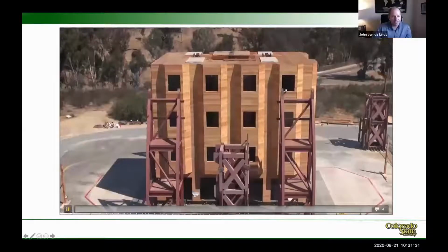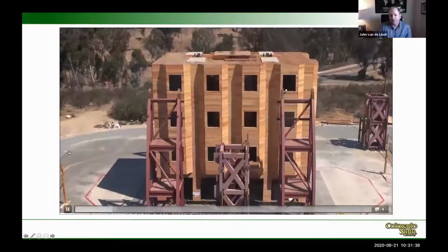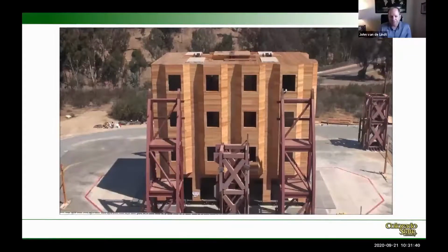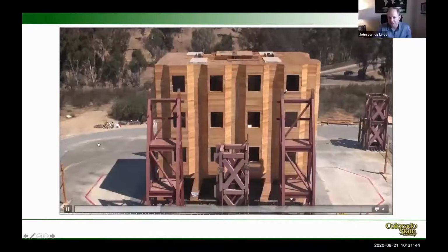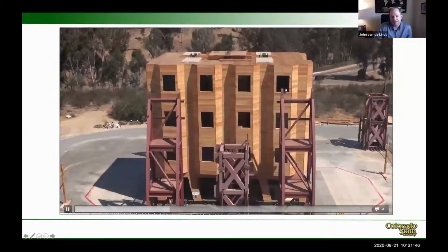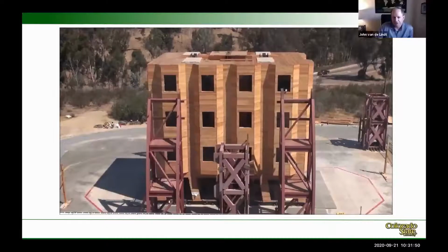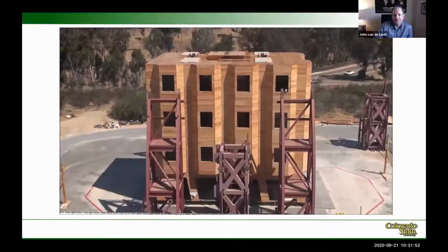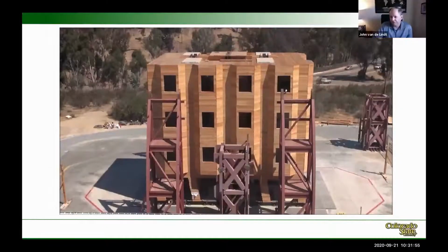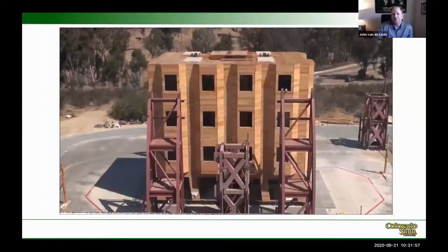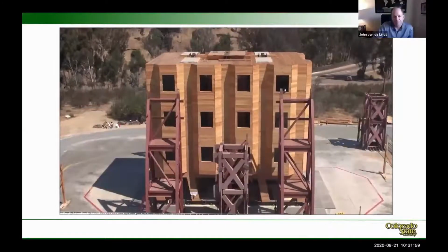So here is the test. I've taken away the sound just because it causes some feedback on these presentations, unfortunately. But so you can see we're shaking with the Superstition Hills motion at scale to MCE. And you can see that bottom story extremely soft. There's 4 one-car garages down there. And remember, no retrofits in here. So our goal is to improve our models of collapse testing.